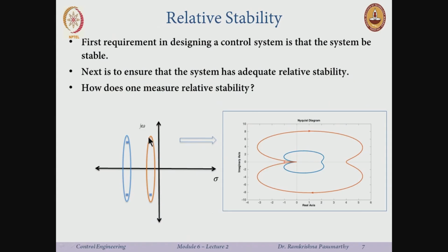Okay, so look at these two things, this brownish kind of color. This is a set of poles here, open loop poles, and these are also a set of poles, right? Now this is my S plane, sigma j omega, and these poles are also called the dominant poles. I'll tell you later why I use the word dominant poles, but let's say the system just has two poles, and I plot the Nyquist for this. So the blue one goes here, and the brownish one goes here.